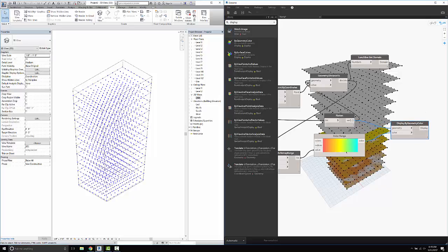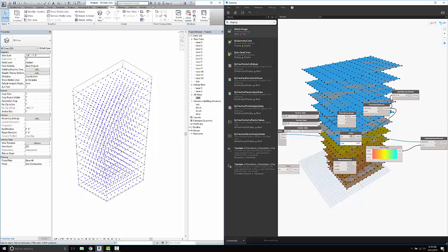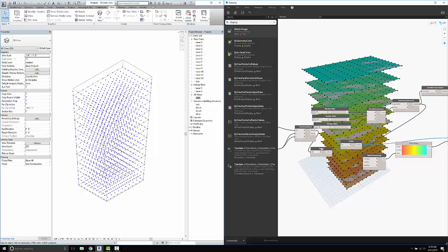And you can see here, I am having this issue with the flattened version of the component that I was concerned with. And I think what we need to do is flatten this list one more time. So I'm going to take the flattened component. You can see automatically once I flatten it again, for some reason it starts to work. I'm going to go ahead and put this fully flattened version in there and into the geometry distance too. There's something fishy going on because I didn't even have to connect the flattened geometry to get the colors completely going, but it seems to be working at this point.